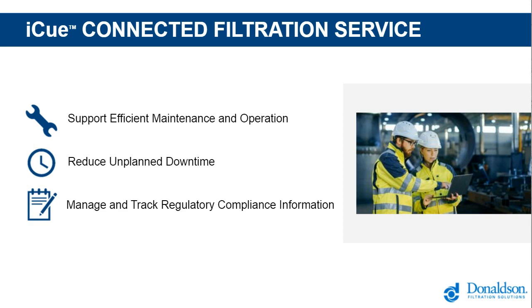Set and configure alerts so you receive notifications when preset thresholds are breached and your collector is operating outside of the preset parameters. And then manage and track regulatory compliance information, access real-time performance data to complete compliance reports, and manage employees' exposure risk by monitoring relative airflow through the dust collector.